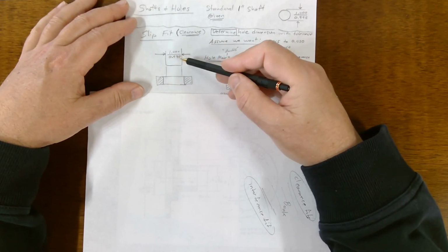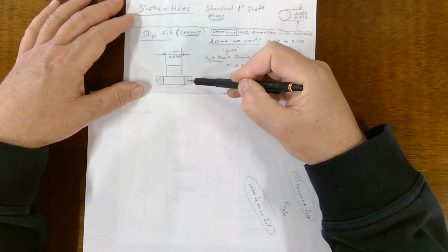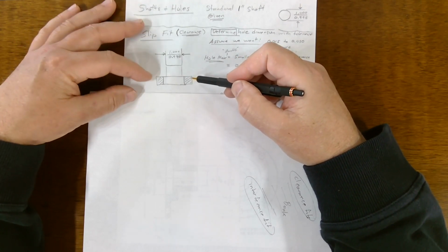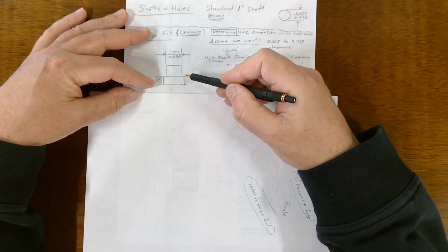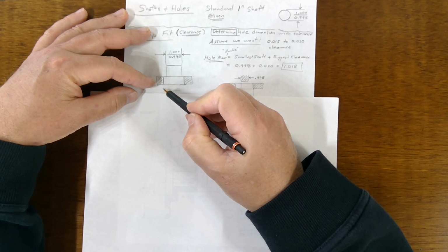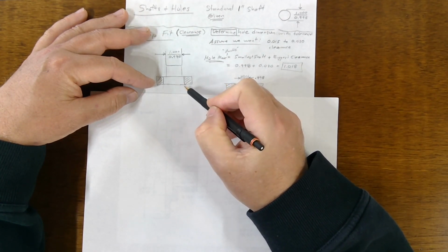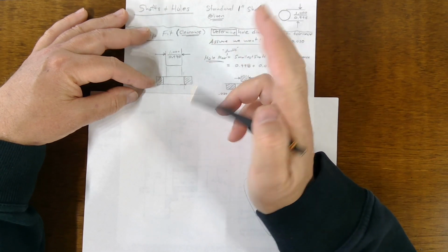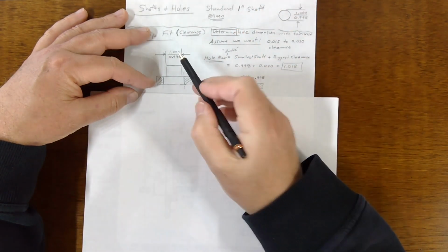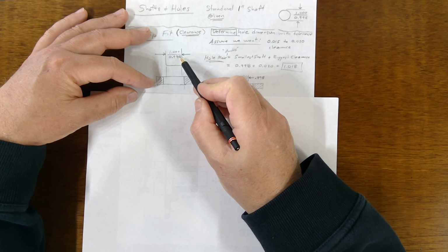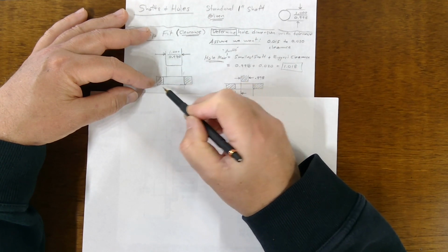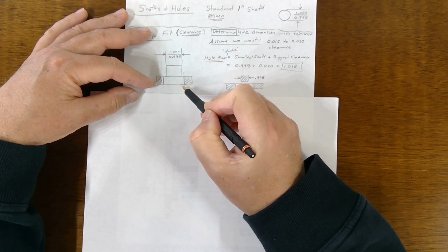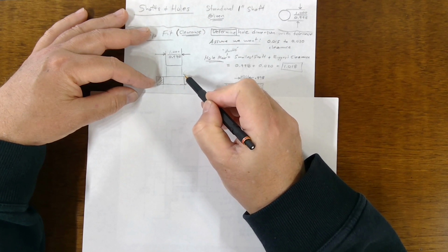You want to take this shaft and put it in this hole. This hole could be a bearing or a coupling or some other piece of machinery. So there's going to be a tolerance on this hole, okay? And there's going to be a tolerance on this gap. Right? There are 3 tolerances involved here. There's the tolerance on the shaft, which is given. There's the tolerance on the hole, which we need to determine. And then there's the tolerance on this gap.